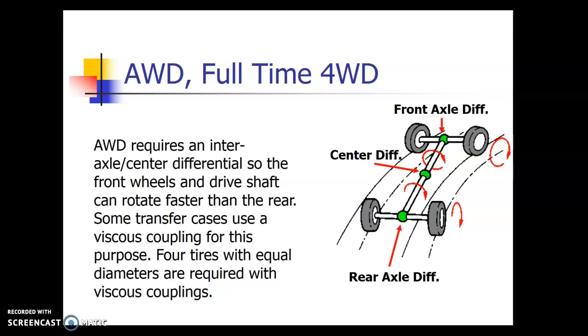Okay. So again, part-time four-wheel drive is what we just talked about before. That's your old school Jeeps, trucks. You wouldn't want to use that cruising down at high speeds on a dirt road or any hard surface because those wheels will slip. That's the way it's designed. It's locking everything, which isn't always the best, but maybe it is. Maybe you want to lock everything, maybe you don't. Just like the differential, it depends on the situation you're in.